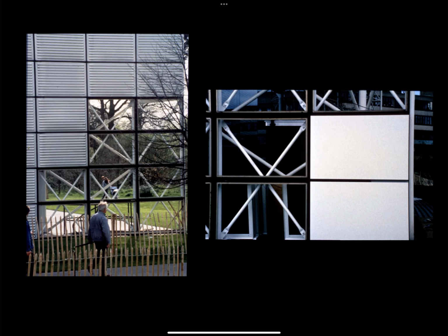So, why did this happen? What was the cause? Well, as I mentioned, aluminum is very antisocial as a material. It doesn't like other materials. And as it turns out, it doesn't like rigid foam insulation. And so there was an adverse chemical reaction between the rigid insulation and the aluminum, and the result is that the insulation corroded the aluminum. So the result was that the entire envelope of this building had to be replaced.